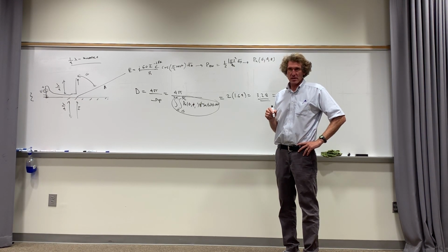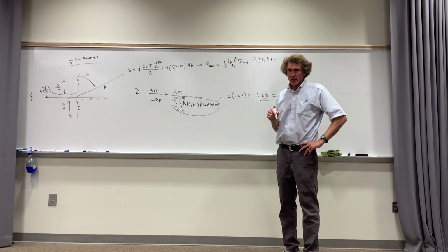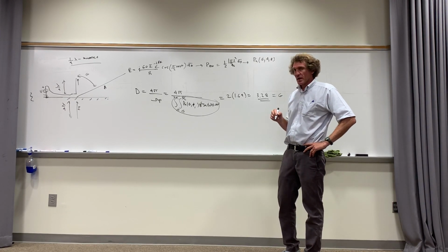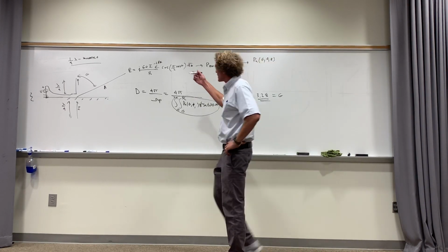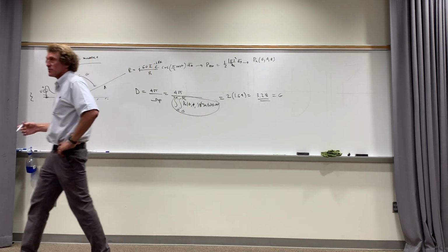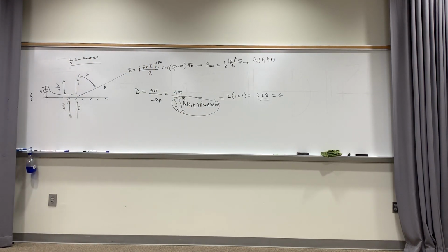Now he has something like that in his book. So that talks about directivity. Now the other thing that's important: since the electric fields above the ground plane are identical, and the power density is identical to that of a half-wave dipole, there's no use in just going through the equations there because we've got them, right? They're before us.